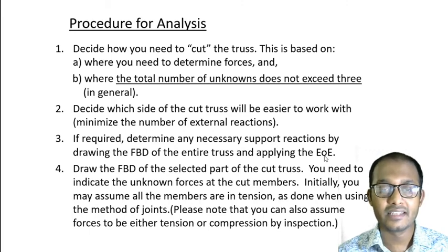If there is any support in the truss, at first you need to find out the unknown reaction forces, because definitely you need those reaction forces while you solve the equations to determine the unknown forces. So this was the first step of our method of joints. If you remember, we have to find out the reaction forces acting on the truss. Then we move to the solutions.